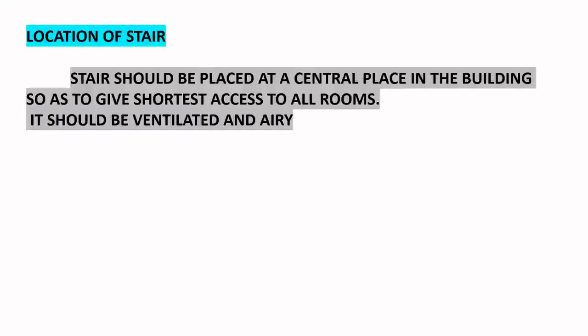The reason is stair should be placed at a central place in the building so as to give shortest access to all rooms. It should be ventilated and airy. So it depends upon our purpose and need. If we need to access all the rooms, we should provide these steps at the center.